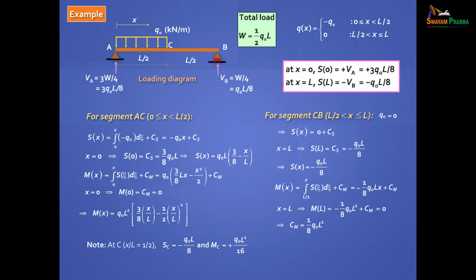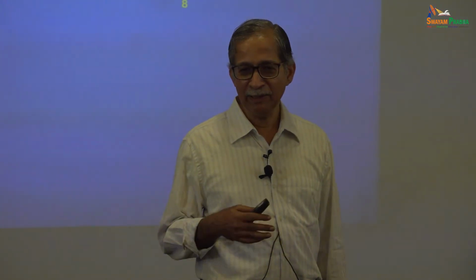You will get another expression for your shear force and your bending moment. Okay, you're beginning with this as your boundary condition at x equal to L by 2. Got it? You can do this. But I strongly suggest don't do all that. That's for beginners. This is a refresher course. We do it the easiest way. What's the easiest way? Free body and equilibrium.